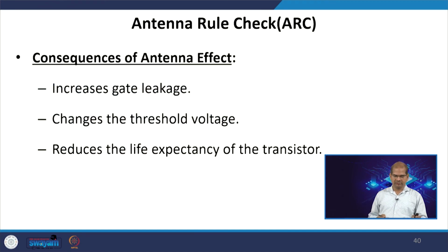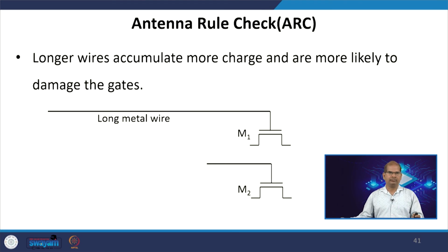So, what is the consequence of that? Your gate leakage increases, it changes the threshold voltage, and it also reduces the reliability of your transistor, because your threshold voltage changes and leakage current increases. So, the reliability lifetime of your transistor also reduces. So, we need to fix those during the design time.